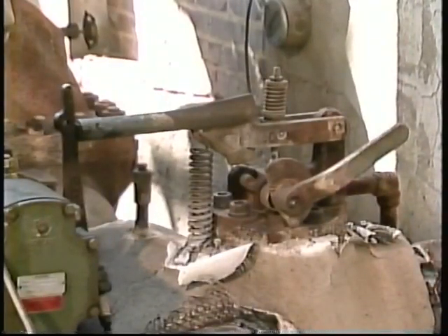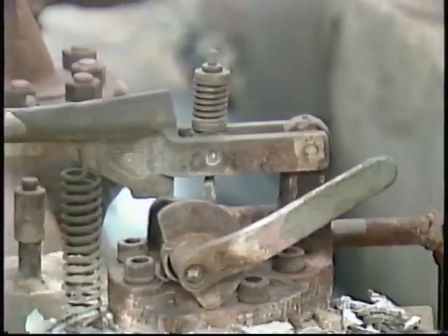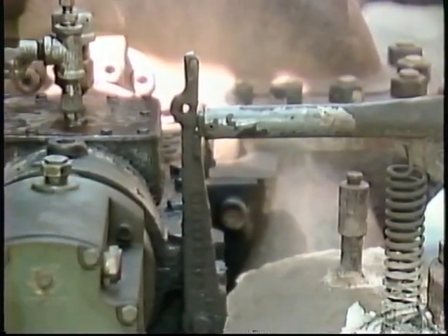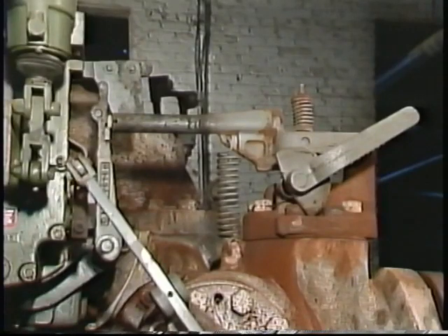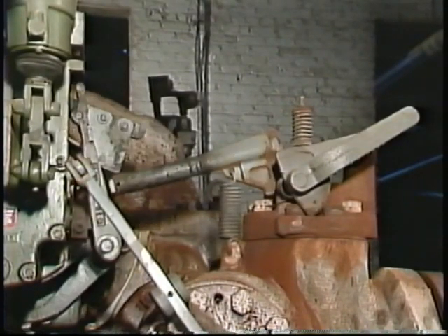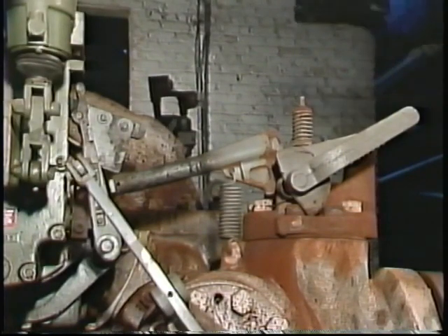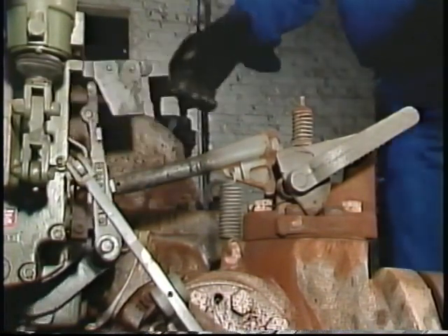Other turbine speed problems involve the operation of the overspeed trip mechanism. The overspeed may trip too soon. That is, it trips too close to the turbine's normal operating speed. If this happens, check to see that the trip latch is holding the lever securely in place. On the other hand, the overspeed may trip too late. In this case, the overspeed isn't triggered until after the set speed for a trip has been exceeded. If this problem occurs, check to make sure the trip latch isn't stuck.